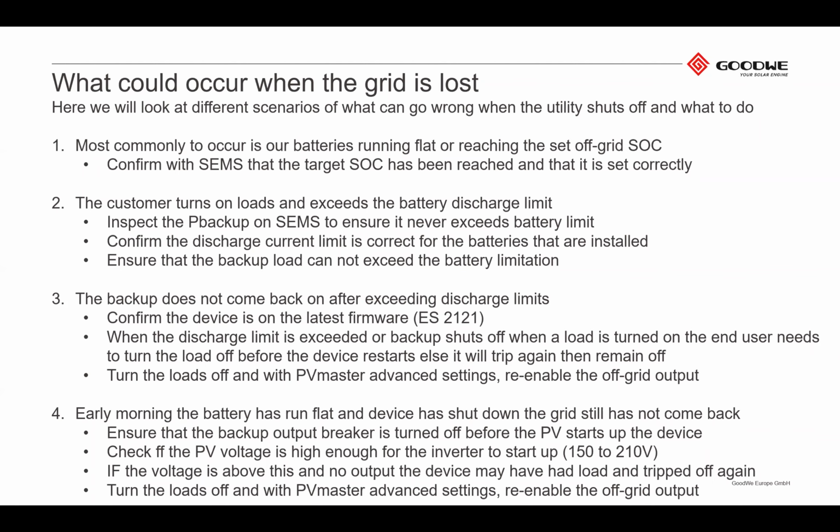this is also something that one can educate your customers on, that should this happen and they're sitting, they know there's been no power, they have a small battery capacity and it shuts off, they should just go and switch the breaker to the backup output off.